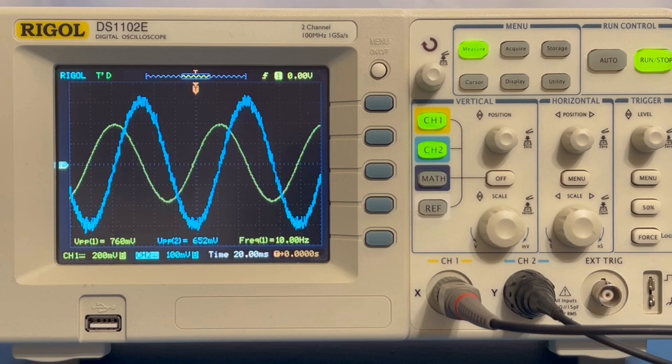This is because the differentiator amplifies high-frequency content more than low-frequency content. This will tend to make gain determinations more difficult, since I'm looking just at the peak-to-peak voltage, and so the noisier the signal is, the more that peak-to-peak voltage is actually contained in the high-frequency noise, rather than the amplified sine wave signal.